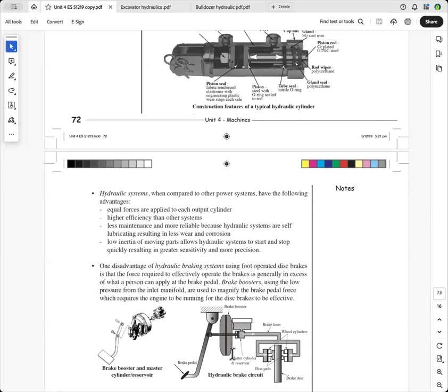And so when you open up this valve, when you put your foot on the brake here, it moves this diaphragm. It sucks this diaphragm along and it helps you with the movement of this piston, which pushes the hydraulic fluid into the wheel cylinders, and these are the disc brake pads there. And so that's how a brake booster works.